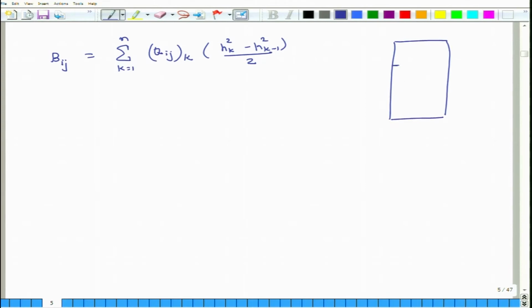So, there are 2 layers, and this is the mid plane. So, z is equal to 0, this is H0. The total thickness is plus 4 to minus 4. So, here z is equal to 4 millimeters, here z is equal to minus 4 millimeters, and here z is equal to minus 1 millimeter. In this case there are only 2 layers. This is the 45-degree layer and this is the 0-degree layer.